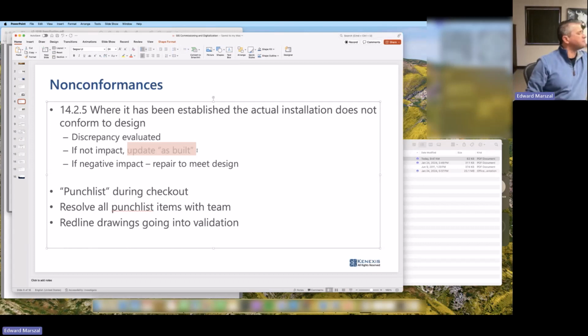All right, so now how does that happen if something got messed up? So I'm going along in my folder. Let me get my pen because now I need a physical pen. And I'm on, let's say, the item, have instrument impulse lines been connected to the right ports? So I'm going to have to say no, they haven't. So I say no, and then over on the action item, I'm going to say switch taps. And under notes and details, I can say something like the taps were switched. Okay, I would elaborate a little bit more if I were actually out in the field. So now I have on my report a no right here, and I've got an action item that needs to get taken care of.